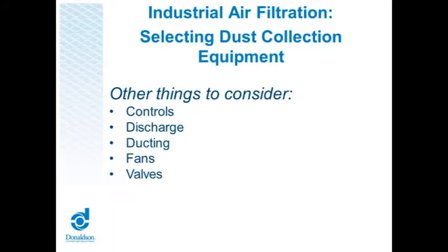Ducting and fans, you know, where am I pulling the dust from? Where am I putting my collector? And where am I safely putting the fan and the discharge of that fan so that either I'm saving money by putting the air back into my building, or I'm dumping it out because I don't want my workers to get exposed or overexposed to what I'm collecting.